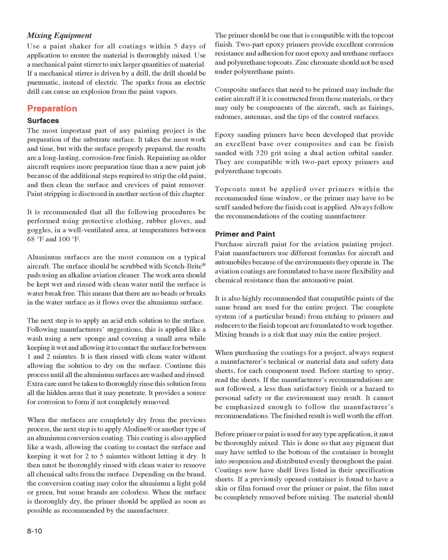Composite surfaces that need to be primed may include the entire aircraft if it is constructed from those materials, or they may only be components of the aircraft, such as fairings, radomes, antennas, and the tips of the control surfaces. Epoxy sanding primers have been developed that provide an excellent base over composites and can be finish sanded with 320 grit using a dual-action orbital sander. They are compatible with two-part epoxy primers and polyurethane topcoats.